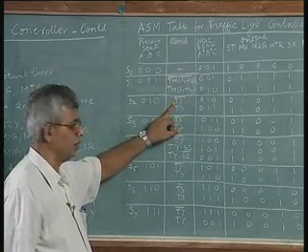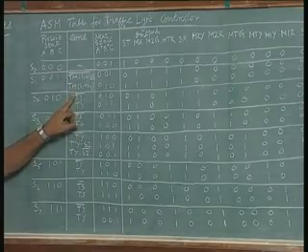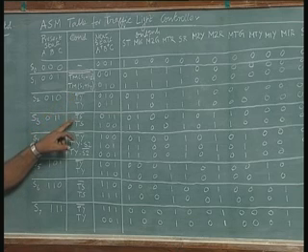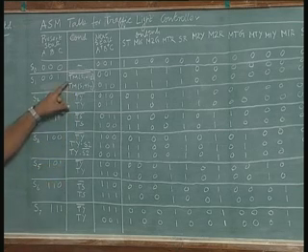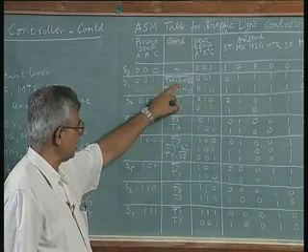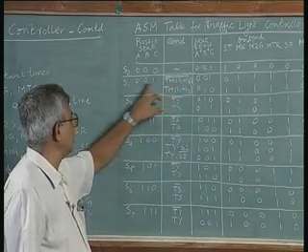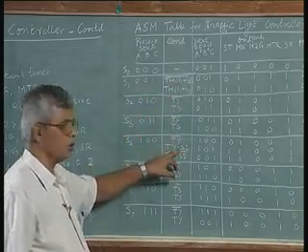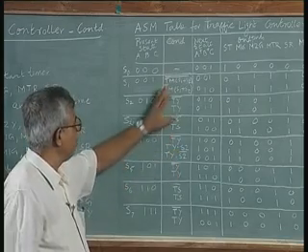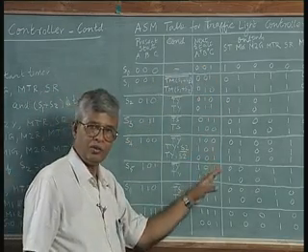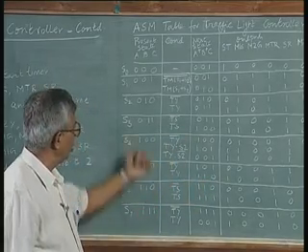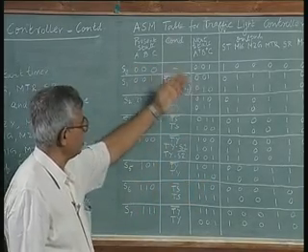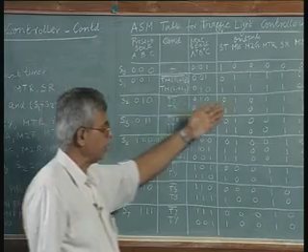Timer yellow not completed, completed. Timer side not completed, completed. Timer main completed, not completed. Sensor S1, S2 both are marked in this first stage, whereas only S2 is monitored in the second stage. Based on that they go to the next state. We drew this ASM, you can correlate this with the ASM that you drew, and from this state the condition to the next state and what is the output in each of these states.